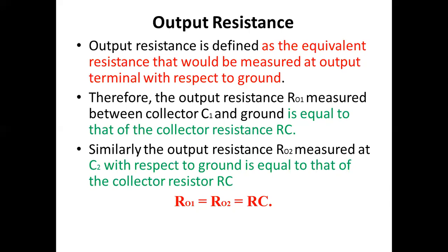At the same time, you should keep the output resistance as minimum as possible. The ideal value of the output resistance should be 0, so that whatever output we get is available as it is to the user, with no opposition. So the common logic is that input resistance should be infinity and output resistance should be 0.